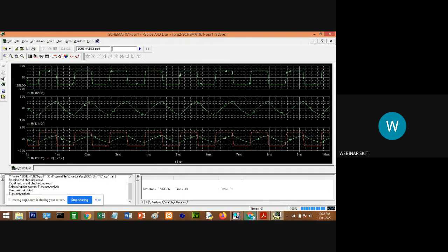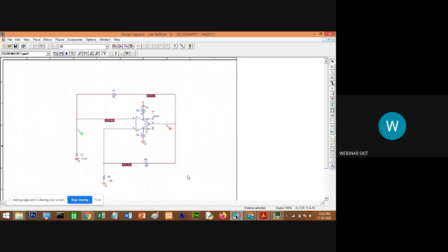You will get this when your circuit diagram is correct, if you don't have any mistake in the circuit diagram. Those warnings I showed you, right, you have to stop until you find the red dot. If you move ahead, you will get the warning. If you continue with that warning, you will not get the exact output sometimes, and you will not get the output at all. Okay, very difficult to debug. At that time, you have to delete all these wires and reconnect them, then execute again, and see, you will get the output.